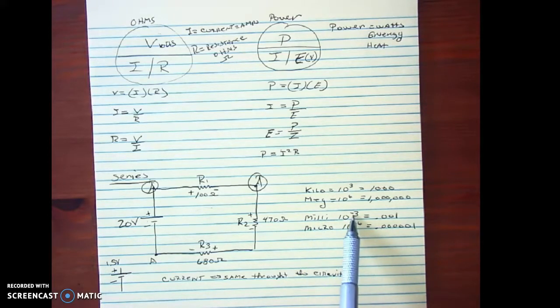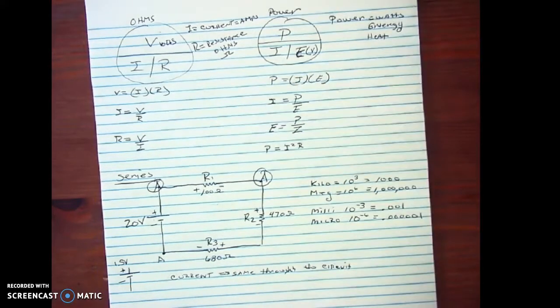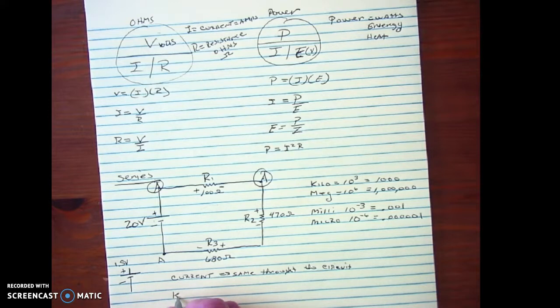So a series circuit, basically you have a DC power source, and this is a single cell battery. But you notice that I use the single cell battery to represent a high voltage. In a single cell battery, we take just a quick glance at this. You have the positive and negative down here. And this is actually 1.5 volts. But if we decide to make this 20 volts using multiple cells, this thing would be stretched out. So, again, what we do in industry is just use a large bar and a small horizontal bar, and we represent that as a DC battery, and we can label it whatever voltage we want.